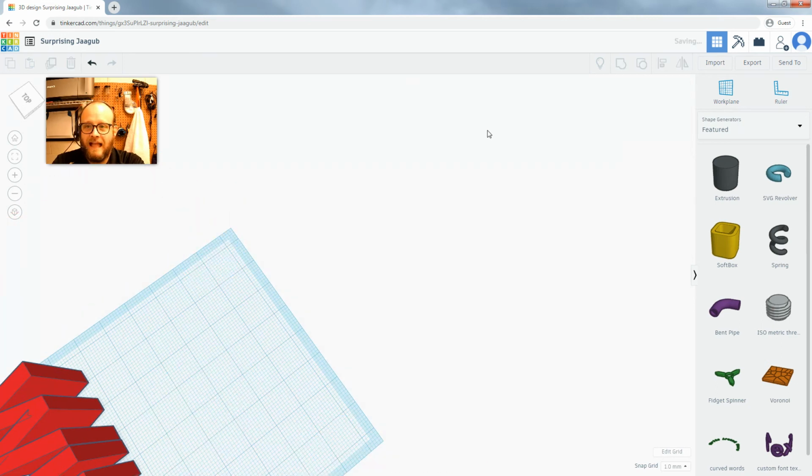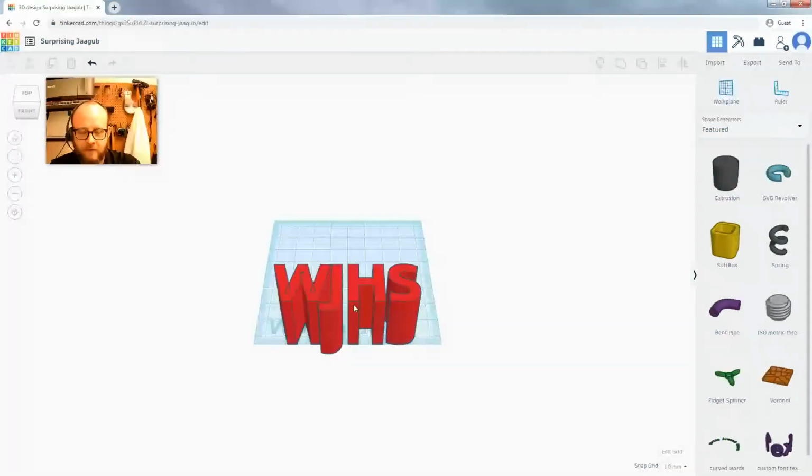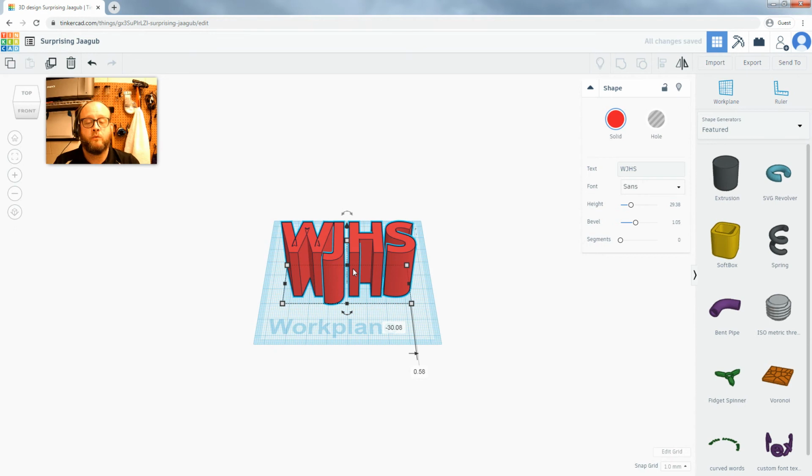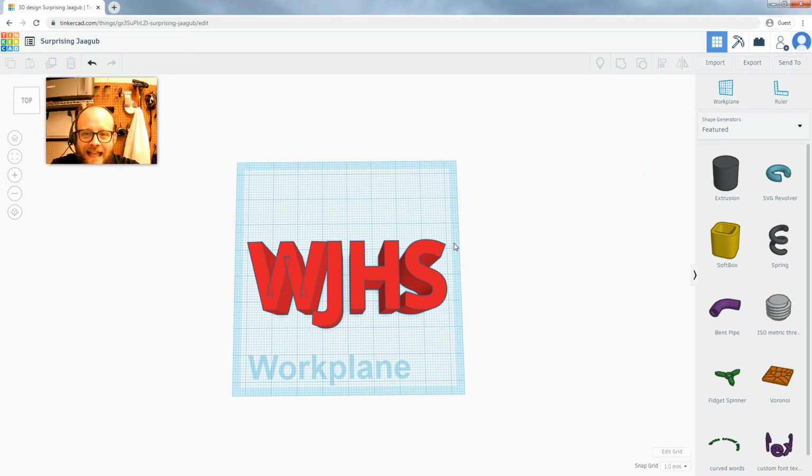Now, as for how we use this with the rest of the work and what you're going to actually have to turn in. So to turn stuff in for this, you're going to actually have to submit a file. So I'm going to come back here and I'm going to go to my home view. So let's say that this WJHS is what I'm going to actually have to turn in. So in order to turn this in, what I need is what's called an STL file, or stereolithography. It's the fancy name for a 3D printable file that we can use on a 3D printer or a CNC machine. It's basically the computer code that tells a machine how to construct this layer by layer.